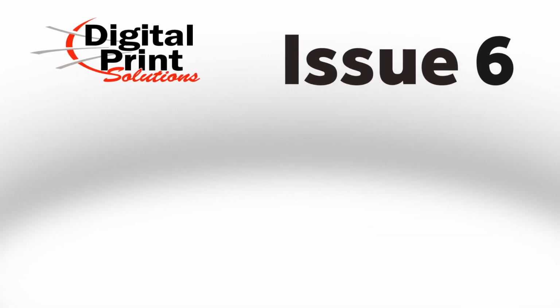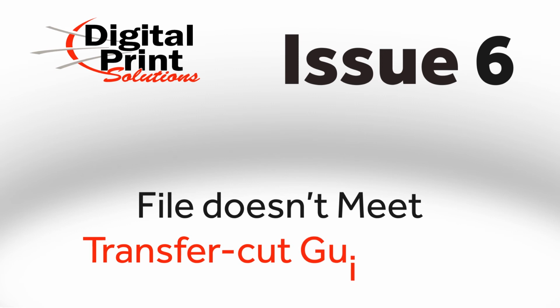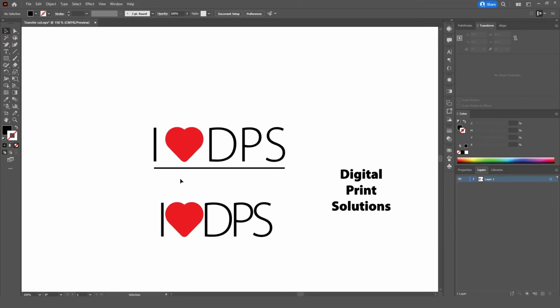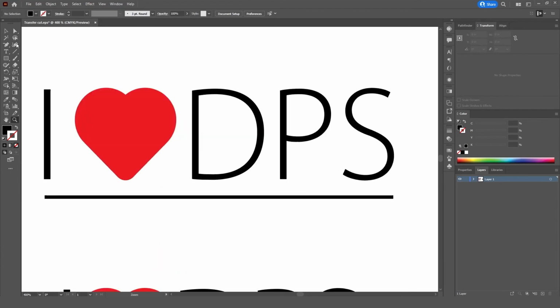Issue 6. File doesn't meet transfer cut guidelines. For issue number 6, we made these files to showcase several common examples of how transfer cut files cannot meet the transfer cut guidelines. This one showcases an example where a file doesn't meet the thickness requirement. Transfer cut files need to be at least 1/8 of an inch thick, which it shows here in your transform panel that it is only 0.03 inches thick.